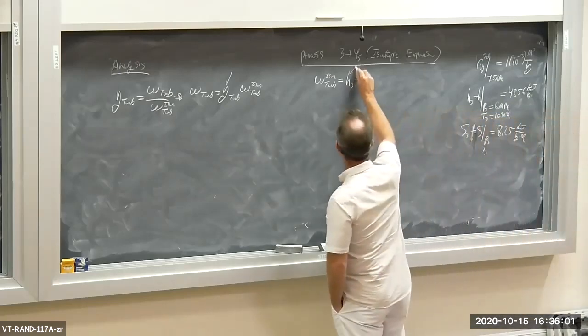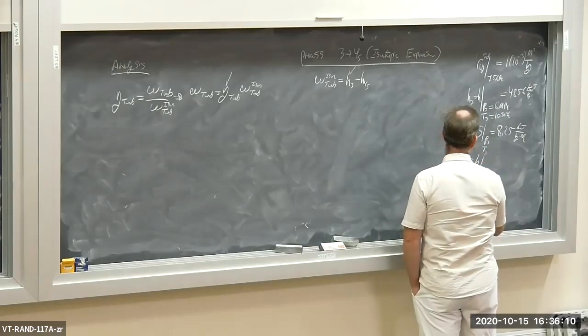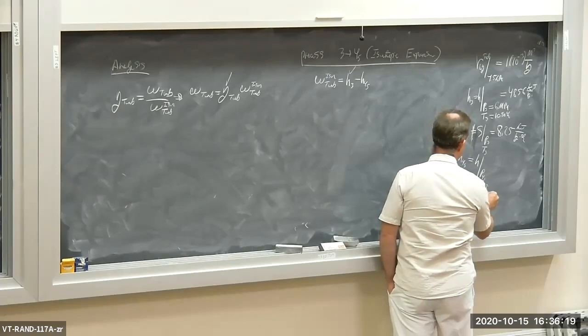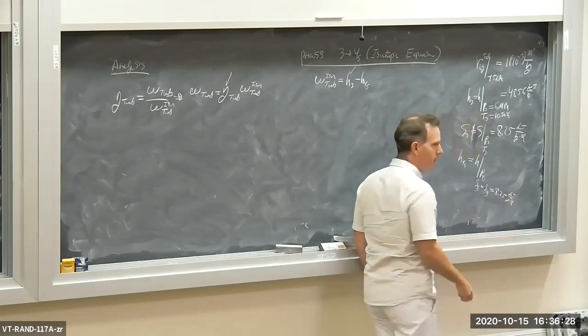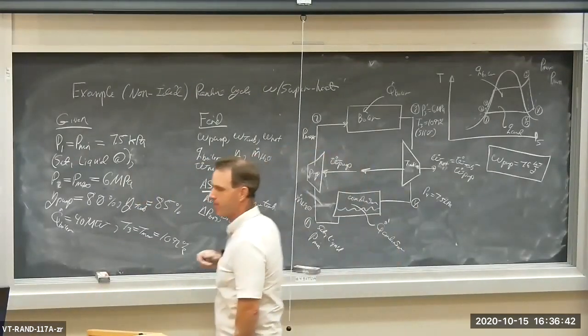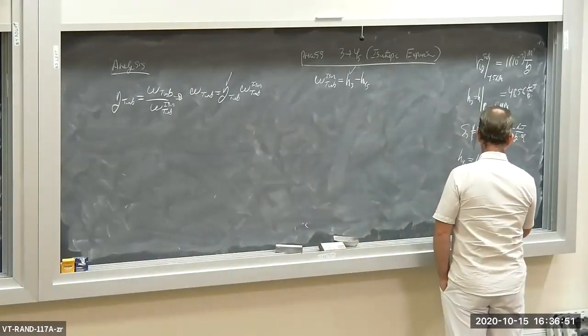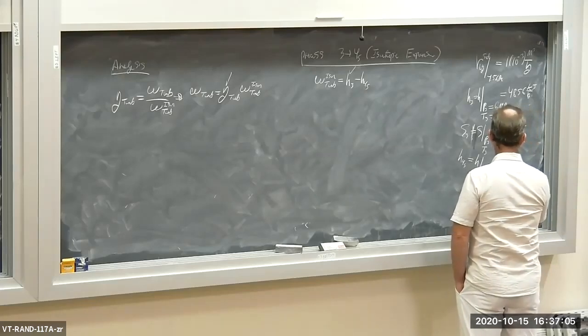Okay, so I have H3 now. So what's H4 sub S? H4 sub S is equal to H evaluated at pressure P4 and specific entropy S4 sub S equals S3. And S3, of course, is 8.25 kilojoules per kilogram degree Kelvin. Okay? And P4 is equal to the condenser exit pressure, which is 7.5 kPa. So that specific enthalpy is 2574.8, or if you like, 2575 kilojoules per kilogram.